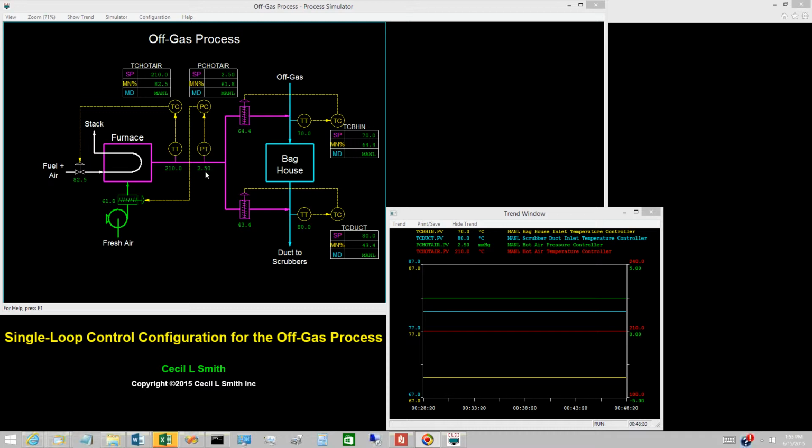To change the heat input, the flow of hot air is varied by changing damper openings. As the flow of hot air changes, the firing rate to the furnace changes so as to maintain a constant hot air temperature.